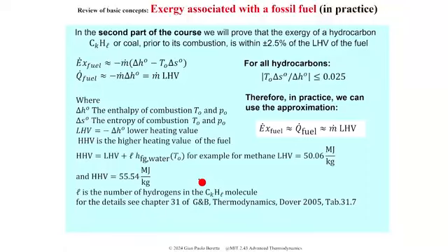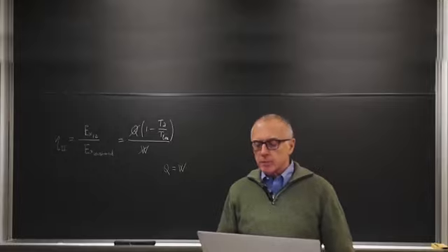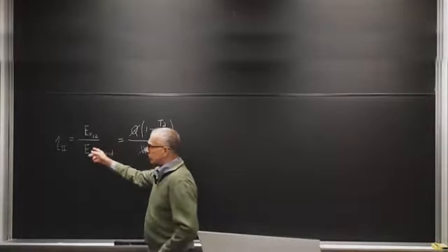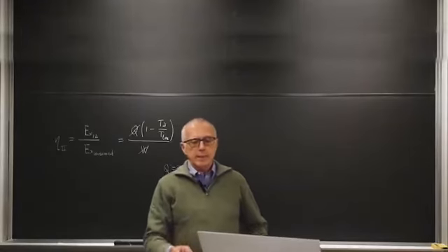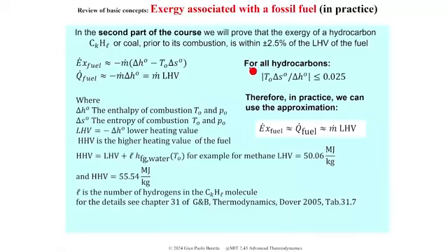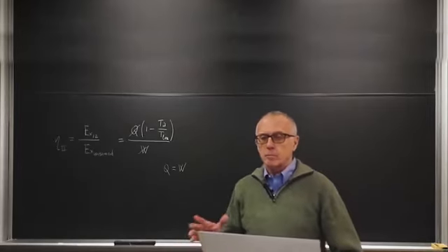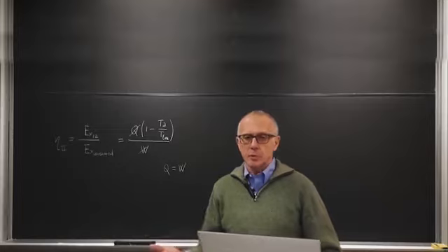The message here for practical applications in which you need to compute the exergy of a fuel, the rule of thumb is that it turns out that for all hydrocarbons, we'll see the detailed list, the ratio of this part of the contribution to that part is small, plus or minus 2.5%.